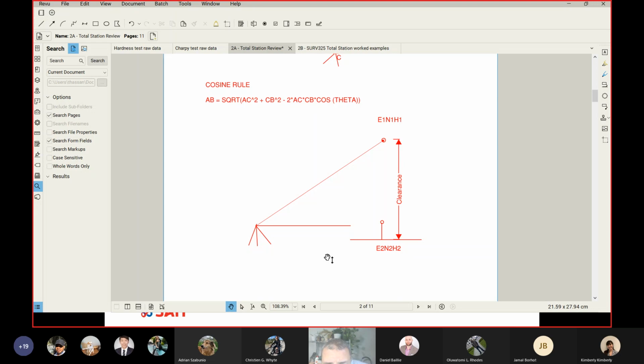Remember, angles don't need any prism. As I said in the beginning, for the angles, you can just have your line of sight to the cable and you can measure the angle. And here we go. So we can measure this angle here to the cable. I will call this one, let's say, V sub C. So that's the vertical angle to the cable. Now, can we also measure the vertical angle to the center of the prism below, like doing this? Can I measure the angle to the center of the prism? Yes, you can do that.